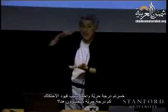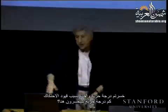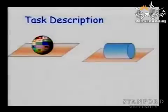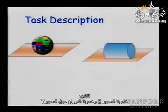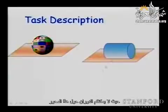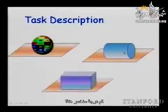2? 5. You lost, yes, 2 in position, and then you still do rotations. You still have those rotations. So you lost 1 degree of freedom by this contact constraint. How many degrees of freedom do we lose here? More than 1? 2. We lost the z-axis, and we lost the rotation about the y-axis, this axis. You cannot rotate about this axis. Okay, how many do we lose here?